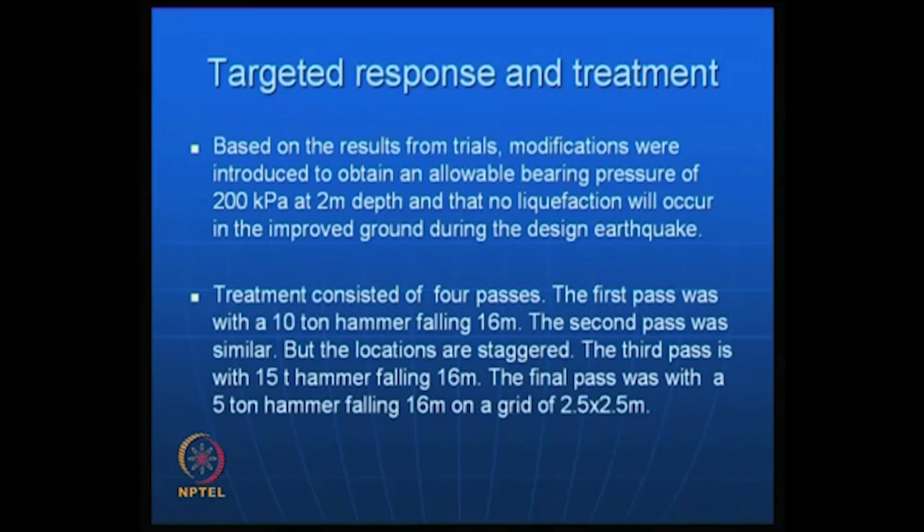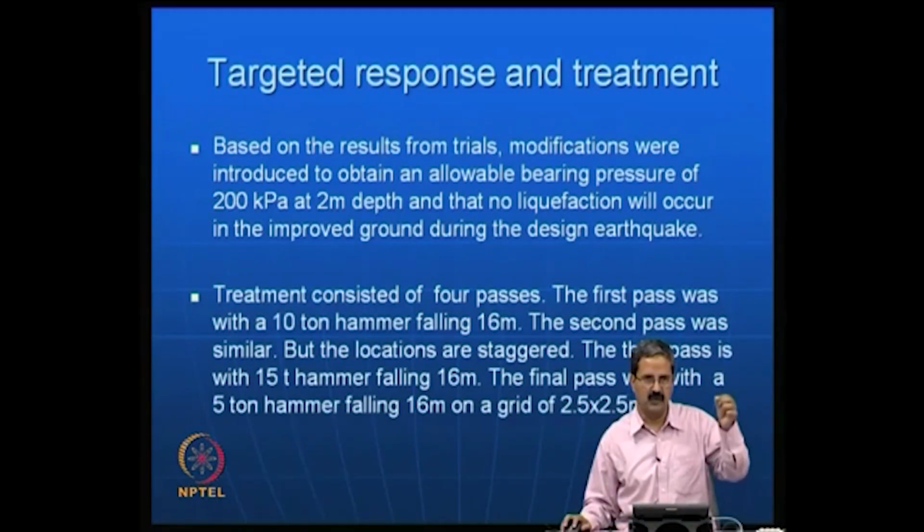So there are some criteria one needs to fix in the particular site. We know how to conduct an SPT test, and we know there are so many corrections in the SPT test. So one should get the correct number, a design SPT value, and then correct it for the energy, like 0.65 or 65% efficiency and all that.